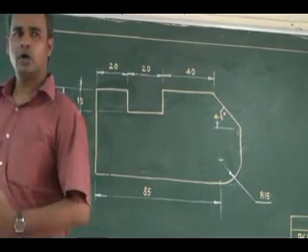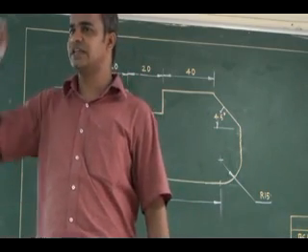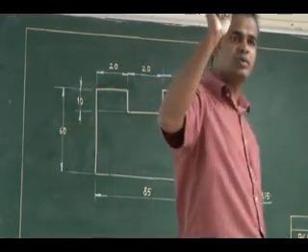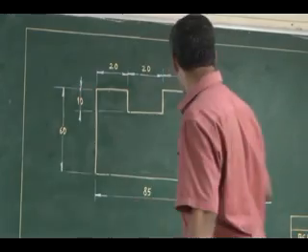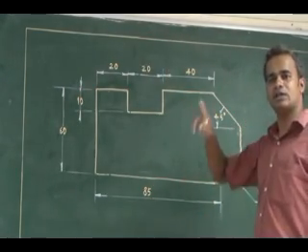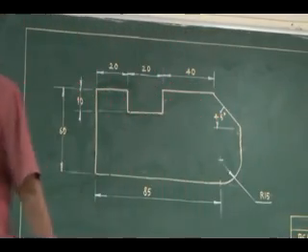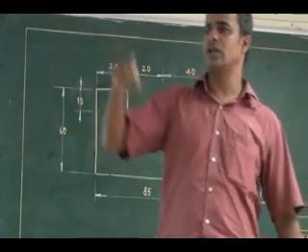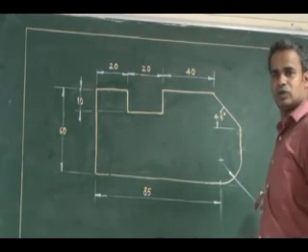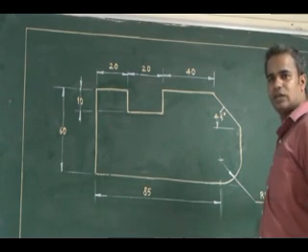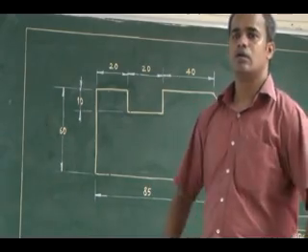Clear? So for angular dimensions, for circular dimensions, or any arc, the dimension line should be extended from the center. Remember that. We can show an arrowhead pointing towards the arc or circle. So for arc, we have to show the dimensions only in radius. Keep it in mind. For arcs, any dimension value you are showing should be in radius. You should not show diameter 30. For an arc, it cannot be diameter 30. You should not represent it with a diametrical value.